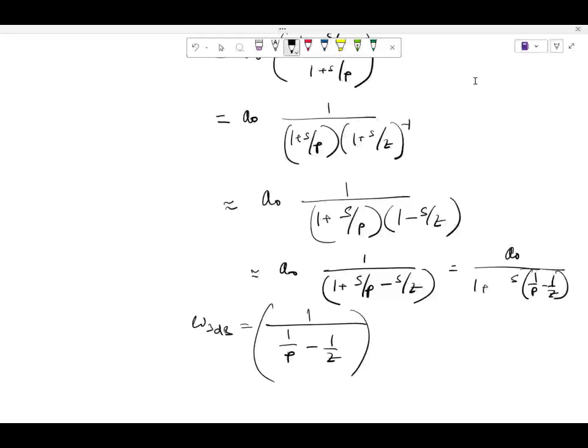But what about if Z has the same value but opposite phase? Then the 3 dB bandwidth should not change, isn't it? In any system, the 3 dB bandwidth should not change based on the polarity of the zero, because the polarity of the zero does not change the magnitude. It only changes the phase. We agree with that, right? So in principle, the magnitude part of your plot should not change, which means the 3 dB bandwidth should not change based on the polarity of the zero.